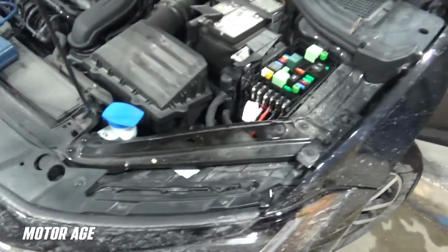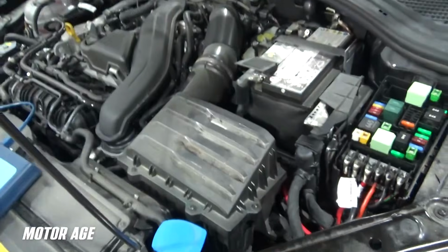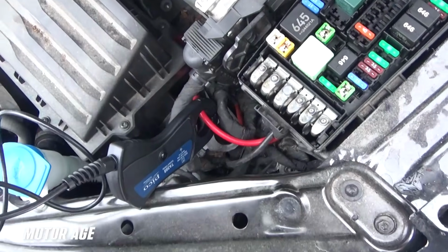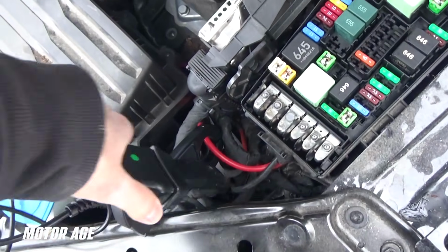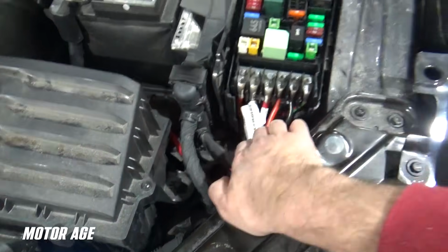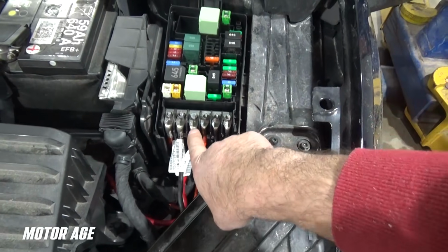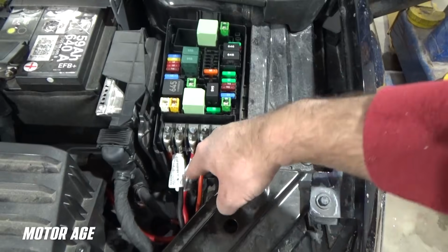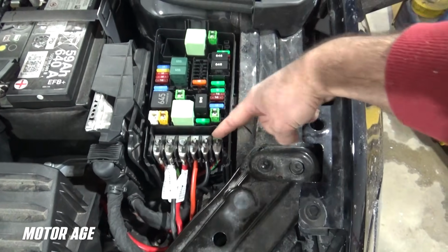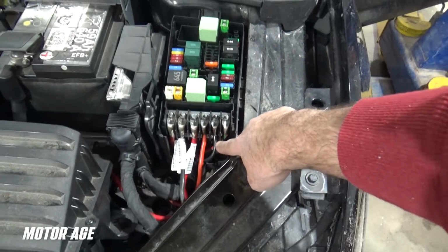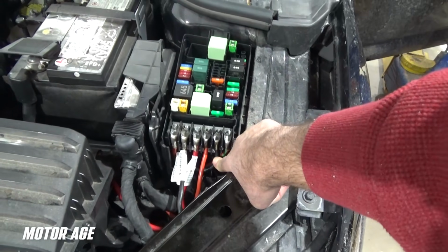So as promised, we're out at the car now, and we're going to strategize, as discussed, by connecting an amp probe to first the battery output. That's our heavy red cable right here. And of course, that's going to lead to the front portion of fuse box A. This is where battery voltage and current comes into the box. And it's split among these 5 remaining terminals, and the question becomes, which of these 5 remaining terminals is the circuit that houses the current draw?